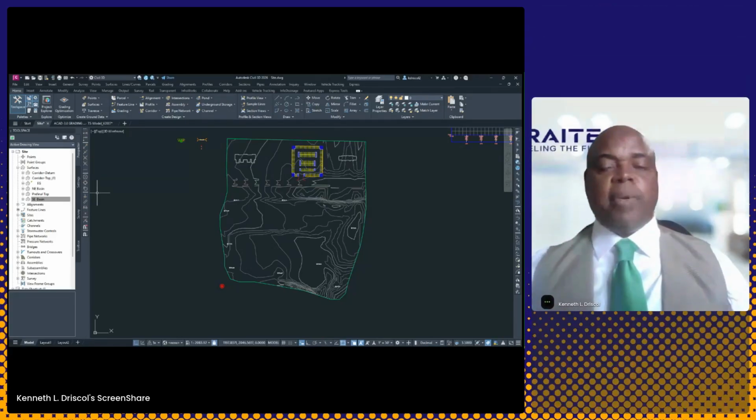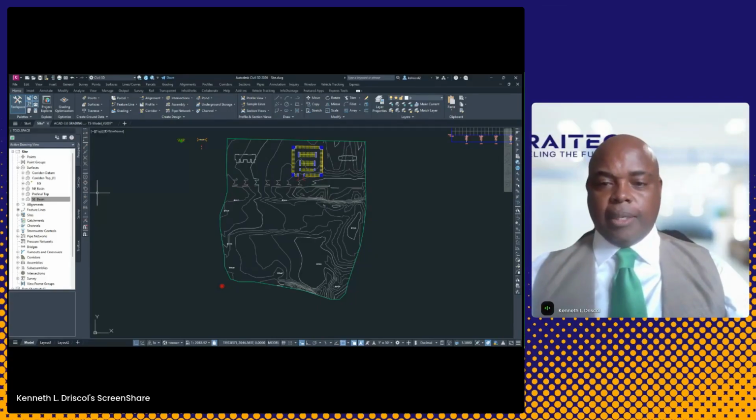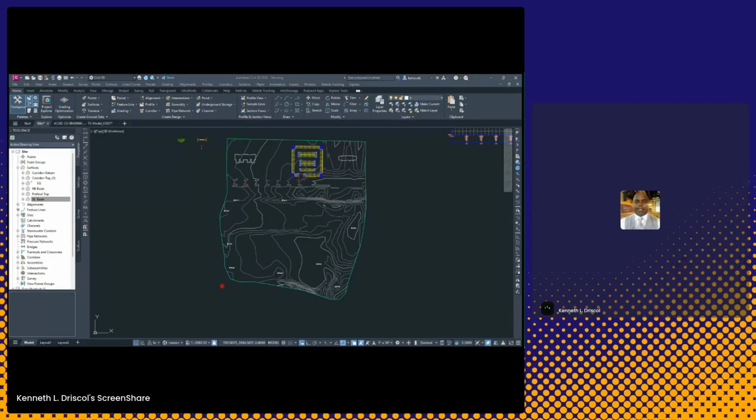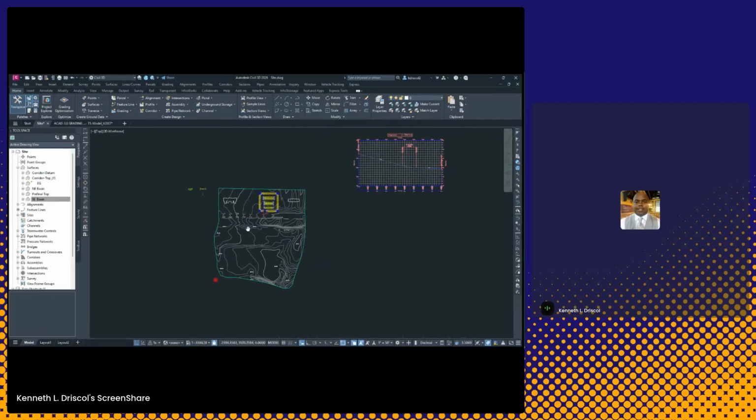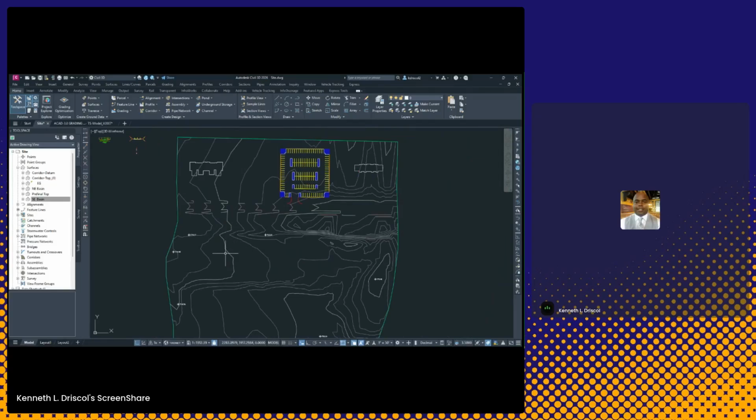Again, we have this site, and typically what I don't try to do is PowerPoint you to death, and you don't need to see me blabbering about this. But one of the things that we want to take a look at is I have this existing ground site. And the first thing in terms of making reference to this site is trying to determine slope patterns and things like that. Slope patterns, flow patterns. I need to be able to examine from this existing ground how we can modify this site, display properly so this site is visually represented with drainage, directions, and slopes.